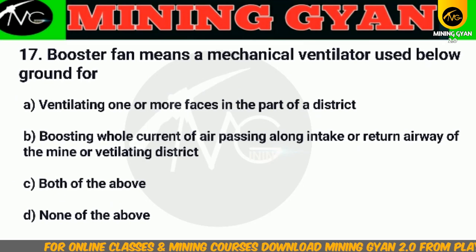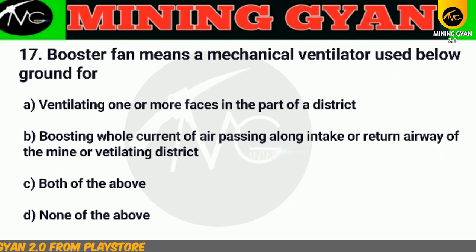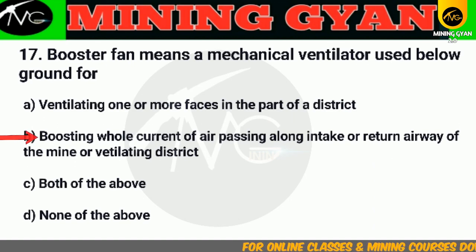Next question is, booster fan means a mechanical ventilator used below ground for A. Ventilating one or more phases in the part of a district, B. Boosting whole current of air passing along intake or return airway of the mine or ventilating district, C. Both of the above, D. None of the above. Right answer is B. Boosting whole current of air passing along intake or return airway of the mine or ventilating district.